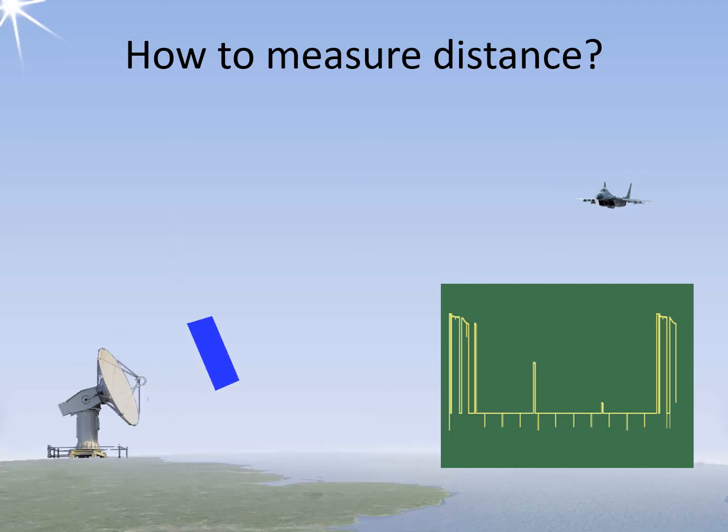In modern computerized displays, this happens similarly, except that the clock for the scale is much higher. It is often in the megahertz range to get more accurate results. At 15 MHz, the distance resolution of the display would be 10 meters. However, an analog oscilloscope displays these pulses as a voltage sum. Thus, the first scale mark slips onto the pulse roof of the fixed target echo.